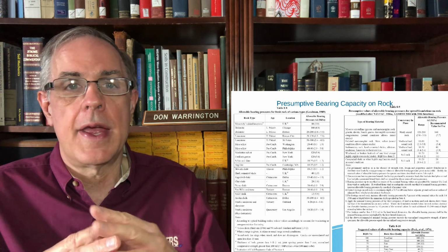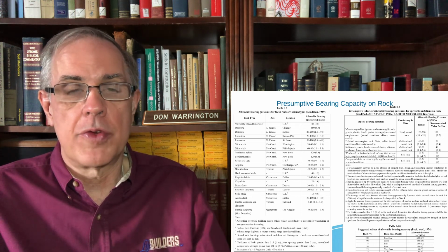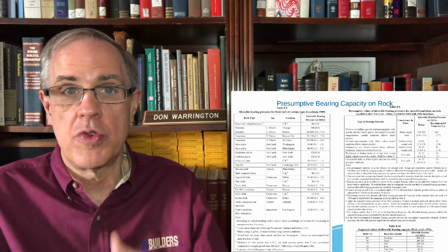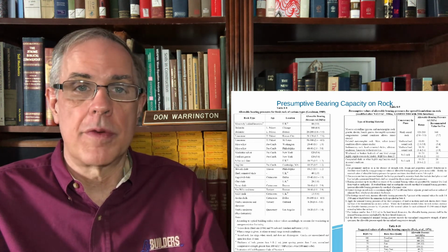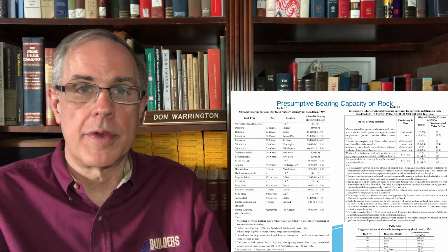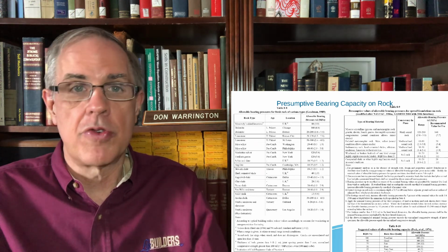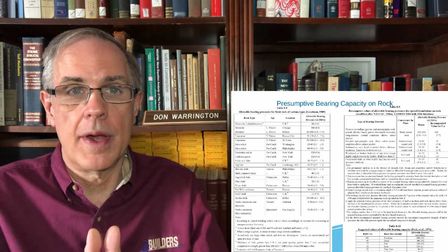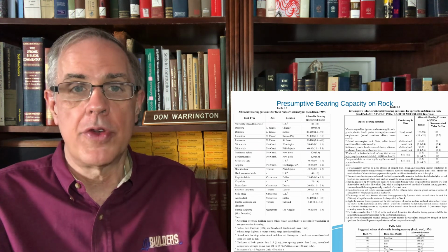You take a foundation, you determine the load. If you have to reduce it using Meyerhof's reduced foundation, you reduce it. Once you reduce it, you take the load and divide by the area, and you get a pressure. You compare that to whatever rock pressures you can endure, and then voila, you either have it or you don't.